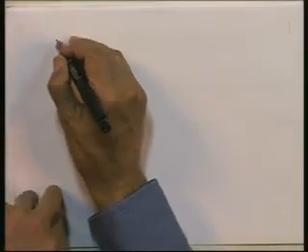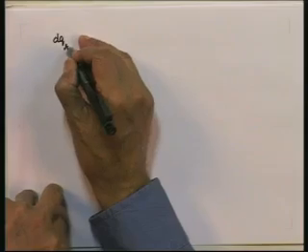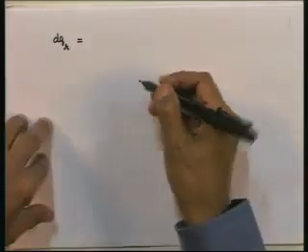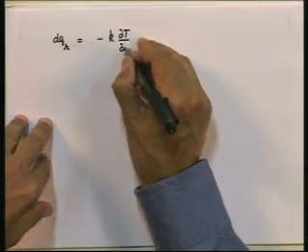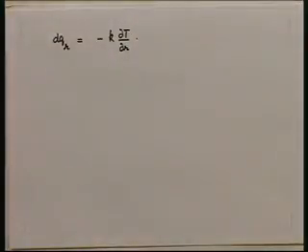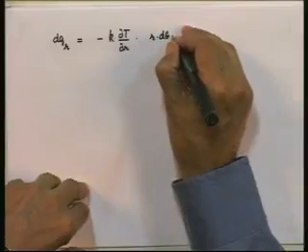We want to put down expressions for each of these quantities. What will we get? We will get the following. Now, I am not going to explain again like last time, I will simply put down the expressions. dqr will be minus k dt dr multiplied by the area through which heat is flowing. The area through which heat is flowing will be r d theta into 1. We assume in the z direction that we have a unit width. So, that is the area.